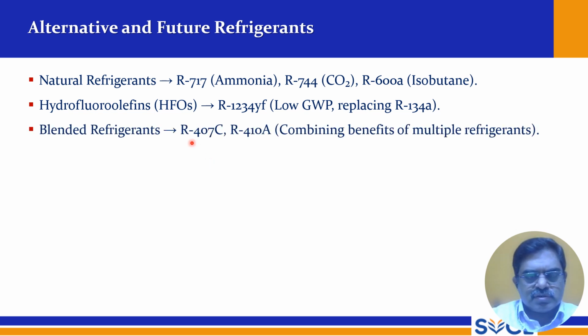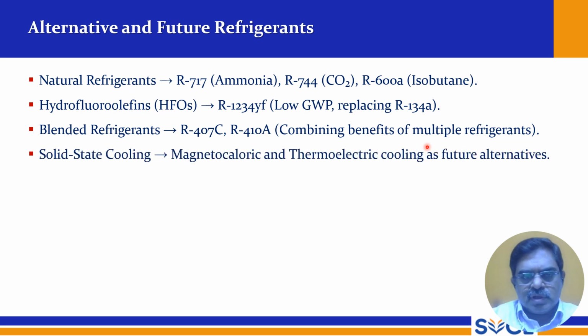Blended refrigerants. These are the blended refrigerants, R407C, R410A, combining benefits of multiple refrigerants. Solid state cooling, magnetocaloric and thermoelectric cooling as future alternatives. So these are also another type of alternative methods coming up nowadays. And solid state cooling is not that appealing one, and maybe in near future a lot of developments may take place in solid state cooling also.